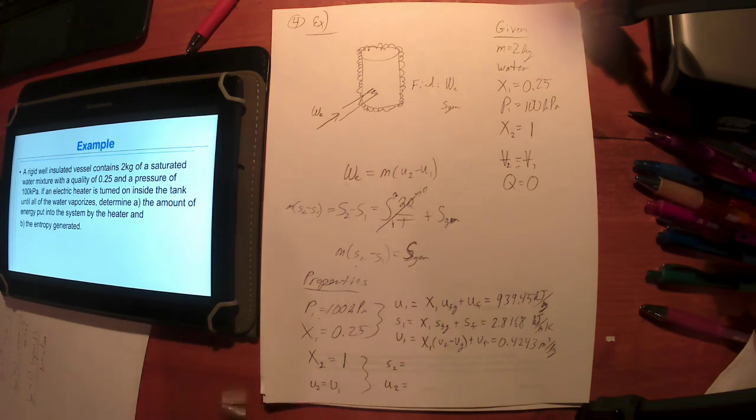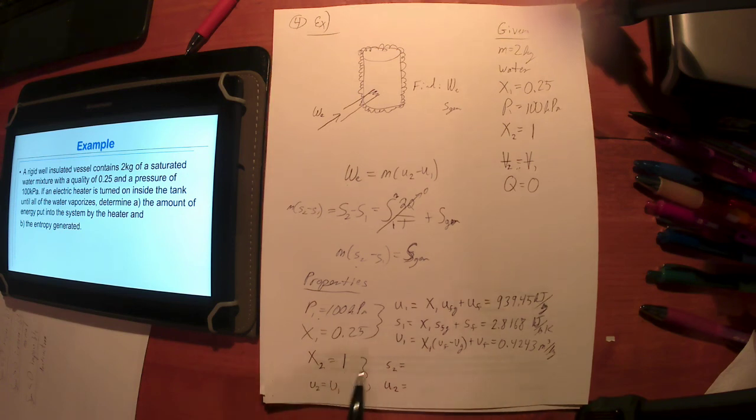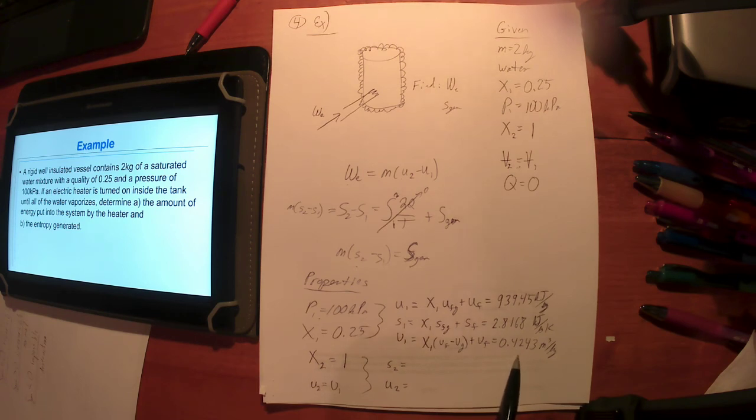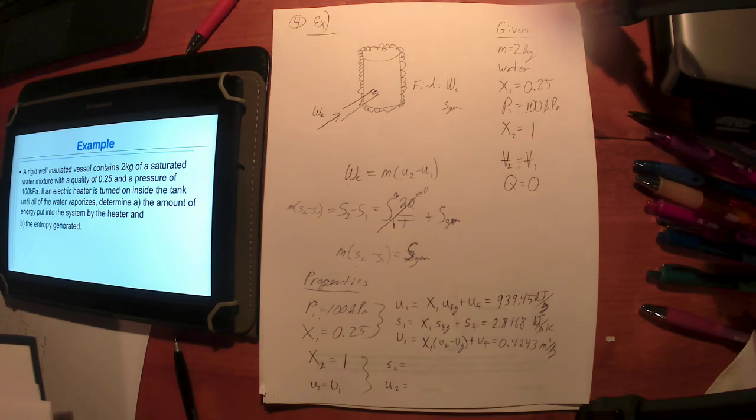Okay, saturated vapor, and we go find this specific volume value and try to find the saturated vapor at this specific volume. You're not going to find this exactly. You're going to be between a couple of rows. So pause it and see if you can find it real quick.